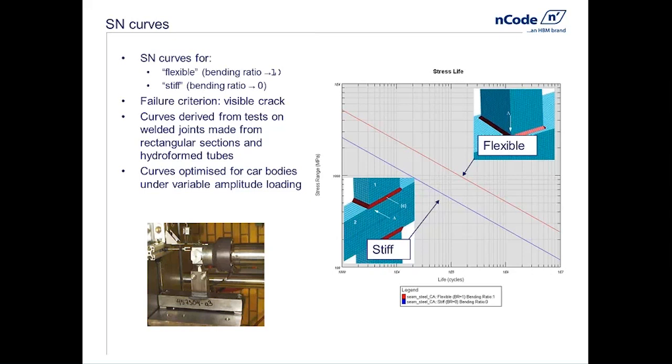The lower curve is a representation of the behavior of welds that were primarily in tension or in membrane. And so in the lower model, the tubes all have the same width, such that the welds themselves, when loaded, are primarily in tension. Now, this tends to make sense when you think of the fact that we're recovering these structural stresses, and those are used basically as just a damage parameter. However, the actual stress at the toe of the weld or at the root location is typically much higher because of the detailed geometry. If one looks at the application of things such as elastic stress concentration factors, besides the stress concentration geometry, the loading mode is also important. And so what we're seeing here is the impact of the loading mode on generating these stresses.